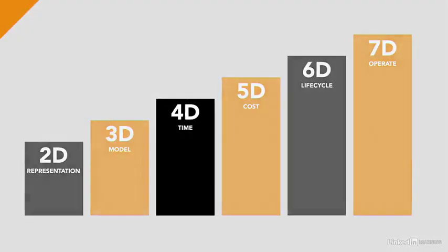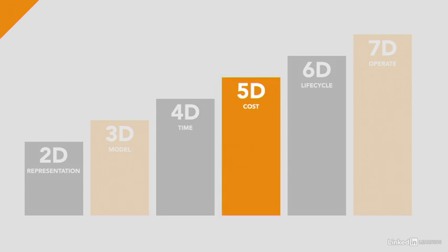At this stage of construction design, another data set is added to the 3D model component. The 4D is the time dimension. This information can be used to obtain accurate program information and visualization showing how your project will develop sequentially, using schedule management software, such as Microsoft Project, when linked into a 4D software such as Synchro 4D or Navisworks. Then comes the 5D, the cost dimension, added to the fourth dimension.